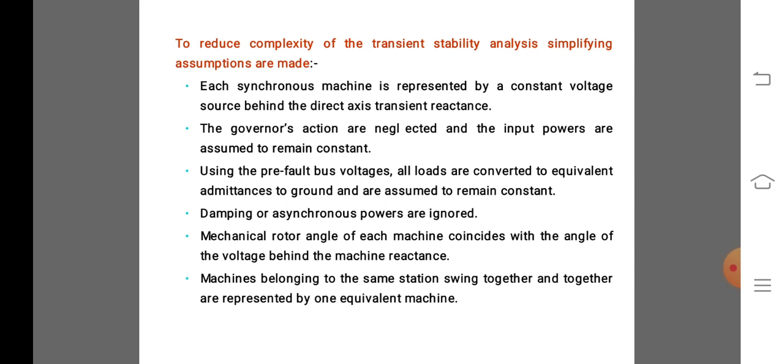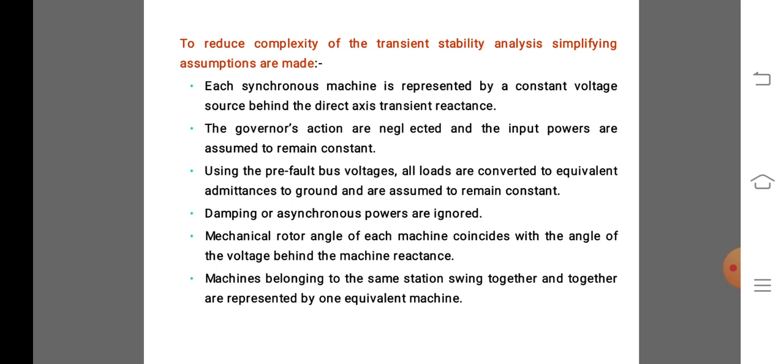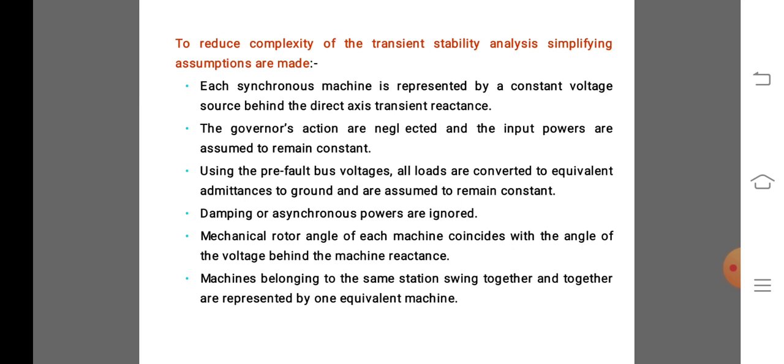Then, regarding the variations in load, the speed of the governor varies as the load is inversely proportional to speed. Finally, the speed of the generator varies and the governor senses the speed and gives a command signal so that the steam input of the turbine is changed relative to the load requirement.